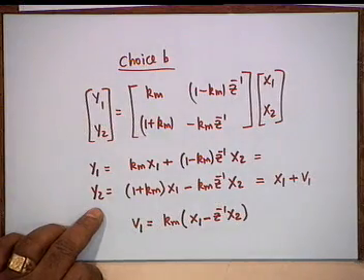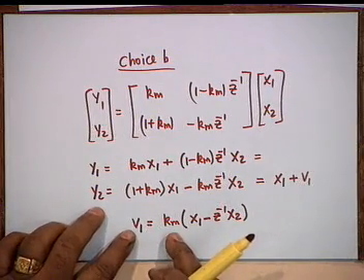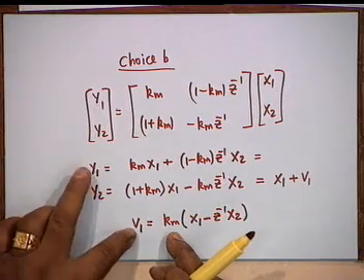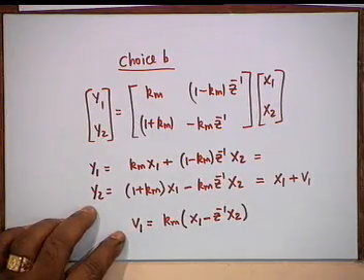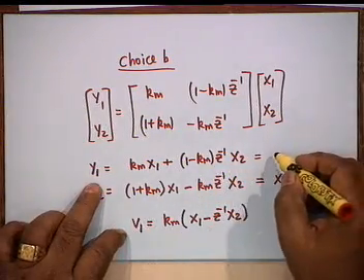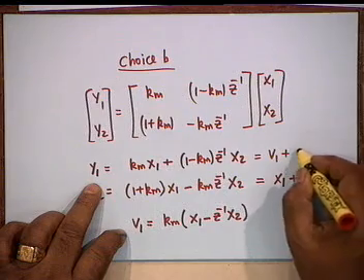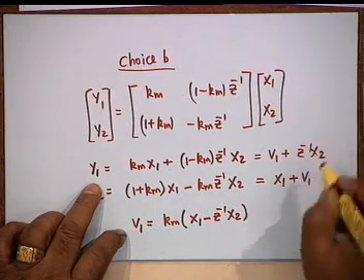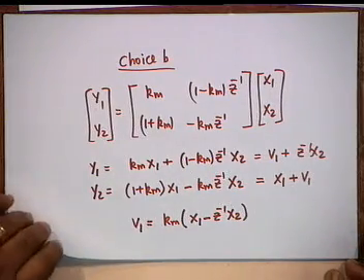Then I should be able to do this. Please understand the thinking that has gone behind this. You see, the multiplier I have used to construct v1. So to construct y1 and y2 I should require no multiplier. That is the concept, that is the thought. And indeed you can see that y1 is v1 plus Z inverse x2, no multiplier here. Agreed? So one multiplier has done the job. Now let's look at the realization.